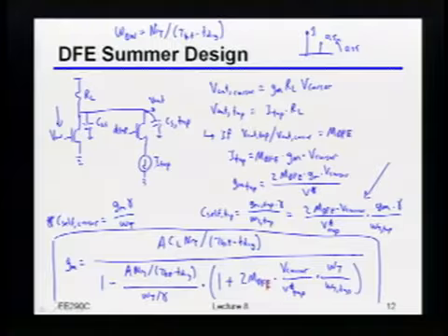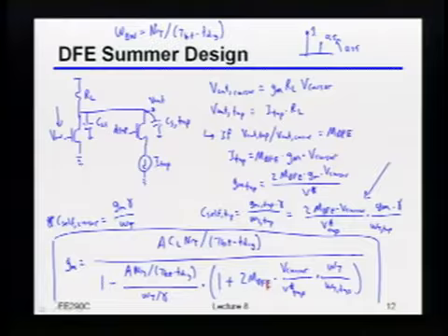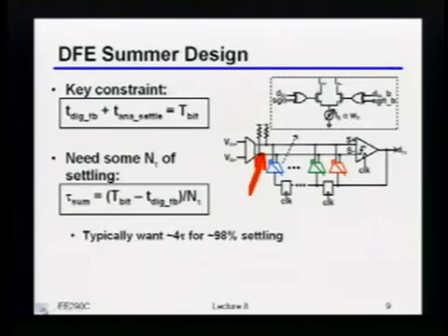Yeah. So if you have more than one tap, which digital delay will you use? Say that again? If you have more than one tap, which digital delay will you use? Okay, so that's a great question, and actually we'll talk about that in a little bit more detail. So, we'll go back to the picture we had over here. What your question is really getting at is, look, there are different digital delays, right? There's one digital delay for that very first tap, and then everything else is a little bit different because that's just straight off of a digital flip-flop. So if I really did something like this, which one are you going to have to use? The shortest one.